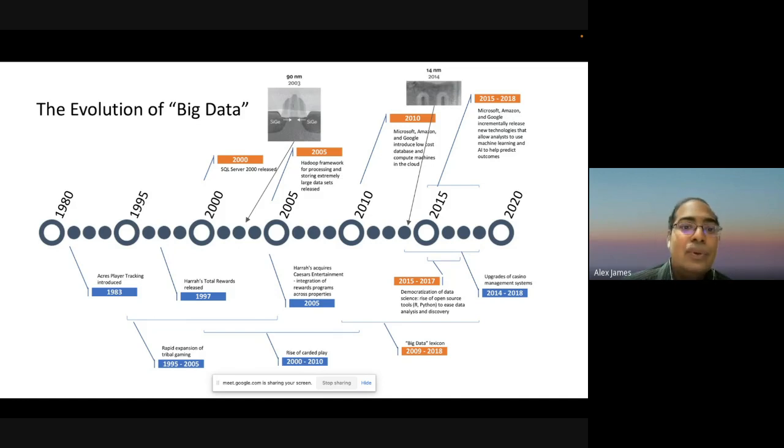And the scaling, if you look at, mostly has been with transistor scaling. It's the digital technologies or digital designs that got scaled. Whereas if you have a processor with analog, or a mixed signal process, they still have a lot of challenges in terms of truly making use of the scaling capabilities of the transistors, mainly due to leakage currents, or the parasitics, or even the sensitivity of the circuits which gets designed. They all become an important factor as we see further.